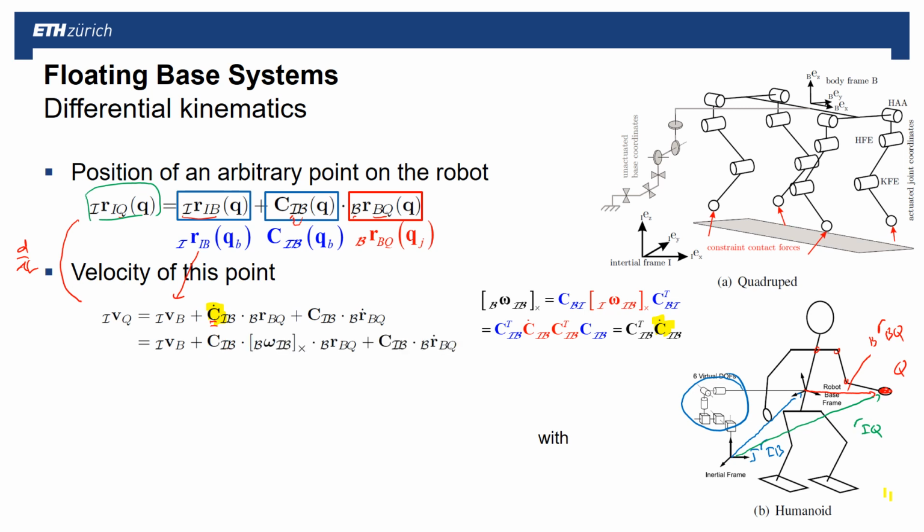By doing so, we can rewrite this whole formulation the following way. So we have this one in here, and then we can change the order. So instead of writing omega cross r, we can write minus r cross omega. This is the move down here. So we change order of these two and put the minus sign here.